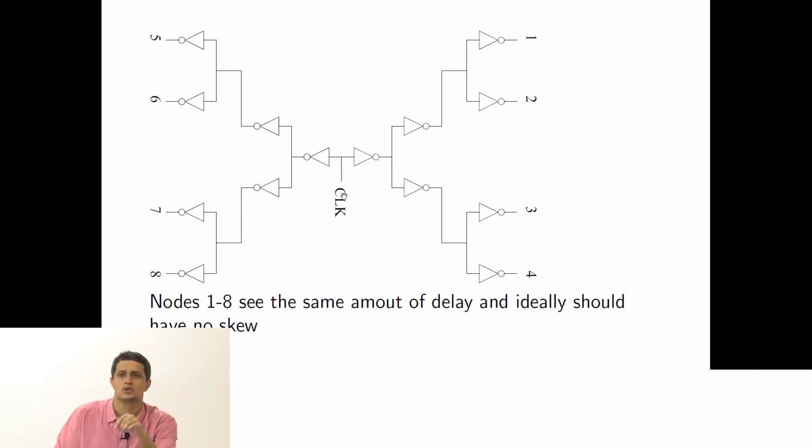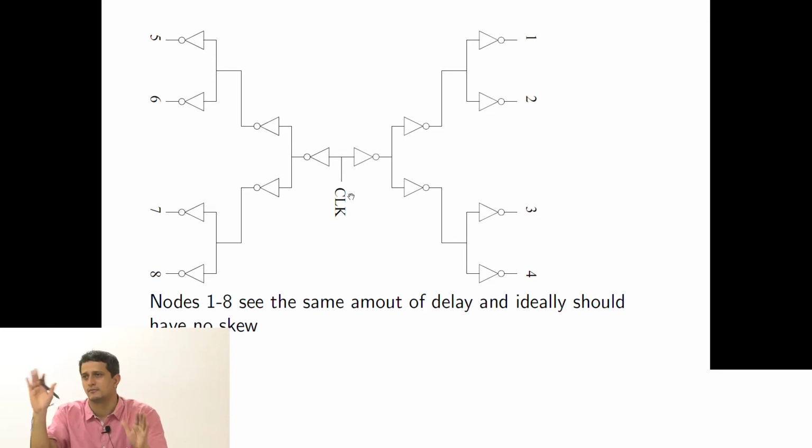So you make a PLL based clock, which is very stable and has no jitter. What is jitter? Basically the clock edge just moves around a little bit randomly. With time, one edge can go this way or that way. So you want to design something with low jitter, and then you distribute this clock through the entire chip in a tree-like fashion.